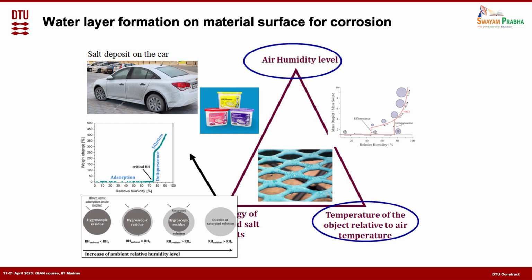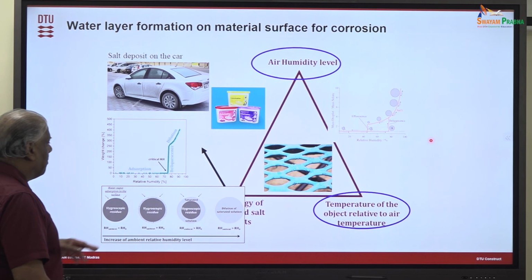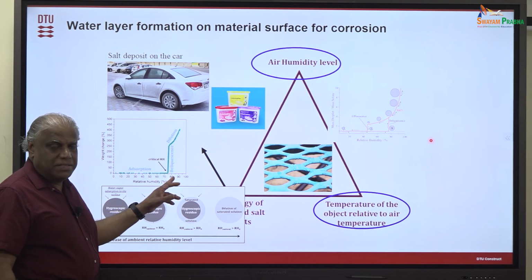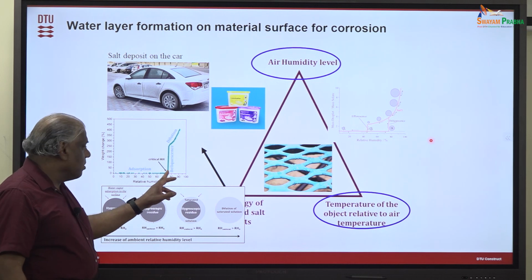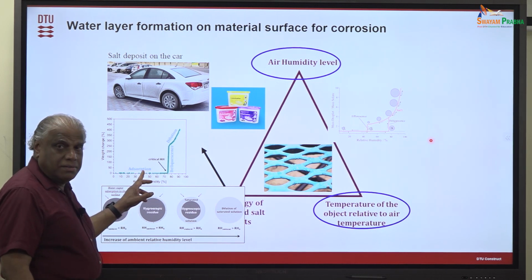So that's much more dangerous. So in Europe, if they are using sodium chloride as a road salt just to melt the ice, then you have a deliquescent humidity level of 75%. But on the other hand, if they are mixing that with calcium chloride and magnesium chloride to make it more effective, this will drop further.